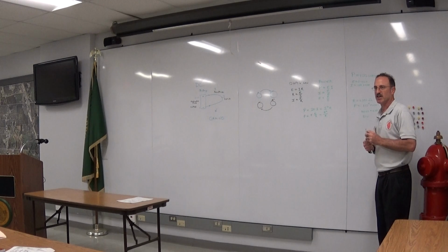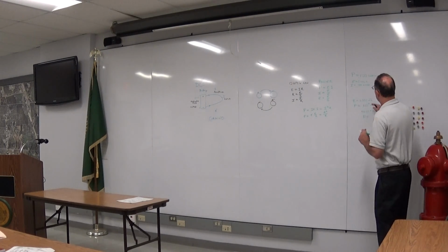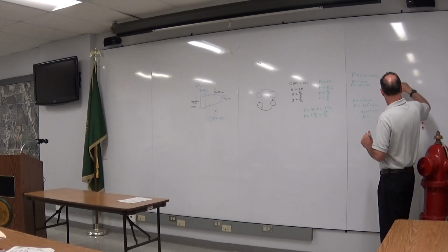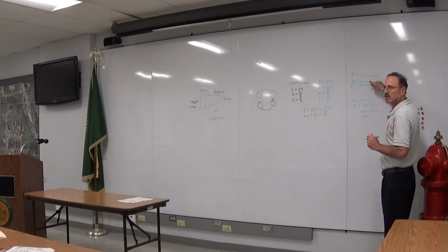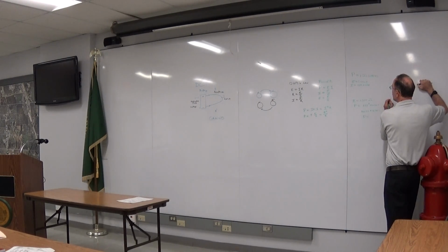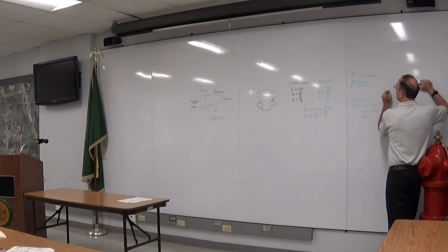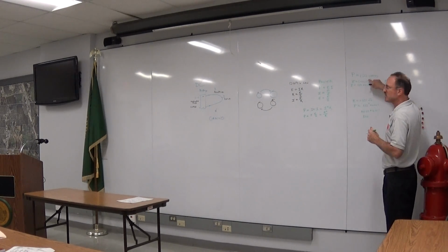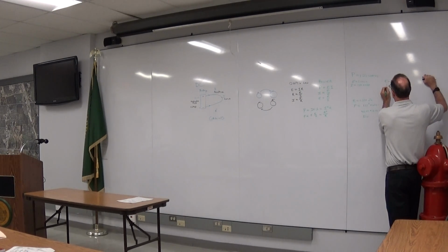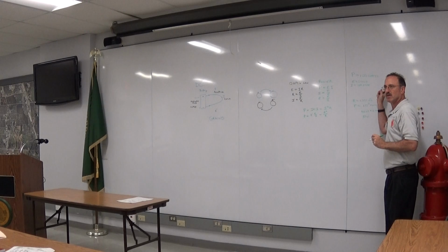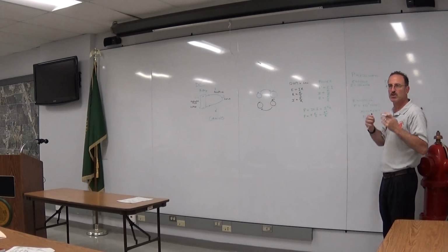They don't like doing that. So now let's say that they're able to convert the voltage up to 100 volts. And for you to get your 100 watts, then you only need 1 amp. It's equivalent in the amount of power that you're going to use at the end.